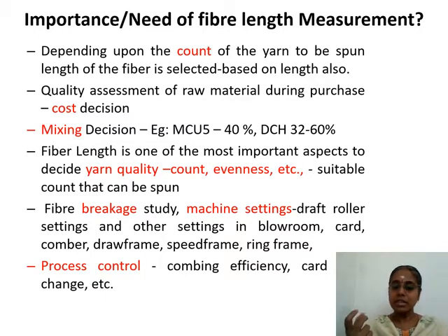And also other settings in the blow room, card and comber, like the spacing between the nip, front roller nip, top comb and bottom comb, all those settings are based on your fiber length.